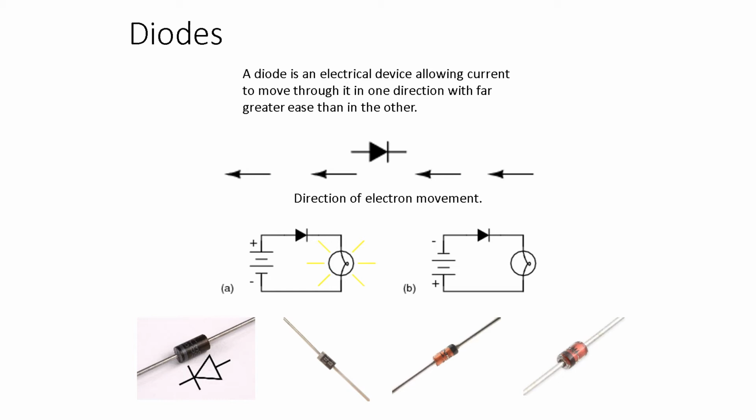That's why we call them through-hole. So diodes, essentially, you can see how they look. They look a little similar to resistors sometimes, but they have a different classification. Often diodes you'll find as black with a little white band around it on the side, and that indicates the direction of the diode, so you have directionality. That's common usually on all diodes, that one of the sides of the diodes will be capped. That way you know if you're plugging it in so that current can flow through it in the right direction, or if you want to plug it in so current can't flow through it in that direction.